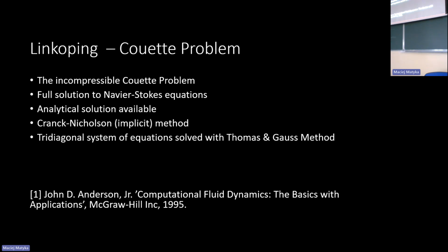If the wall is fixed, that means you have to assume some kind of boundary condition, okay? Because we are basically solving partial differential equations. So you need to know what is on the boundaries, okay? So for this boundary, we assume the so-called no-slip condition.